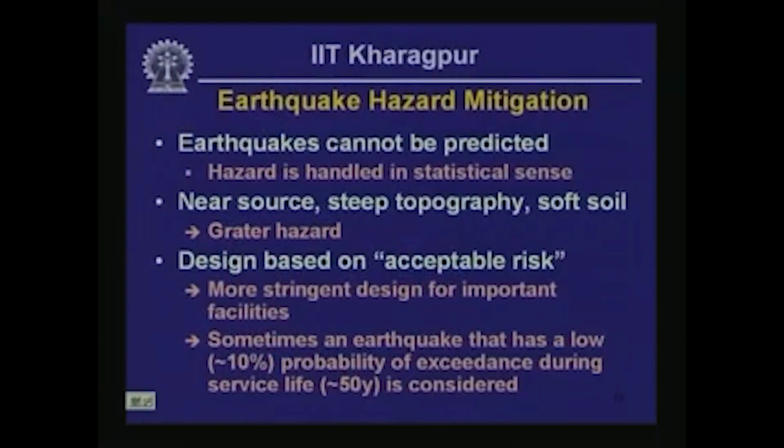Second aspect that you need to consider here, which we already discussed, is that sites that are near source, with steep topography and soft soil typically are more hazardous than the sites that are far away from the earthquake sources, sites that are underlain by stiff soils or hard rock, and the sites that are located in areas with a flat topography.